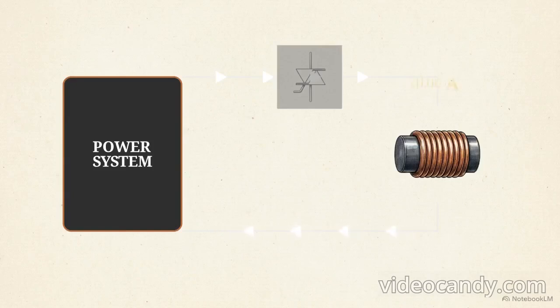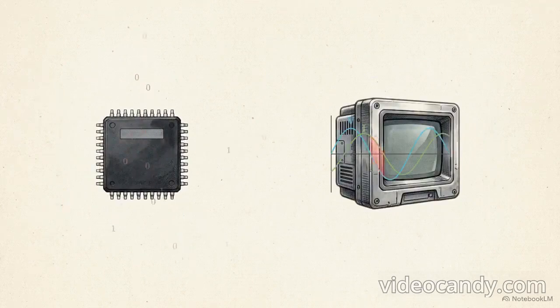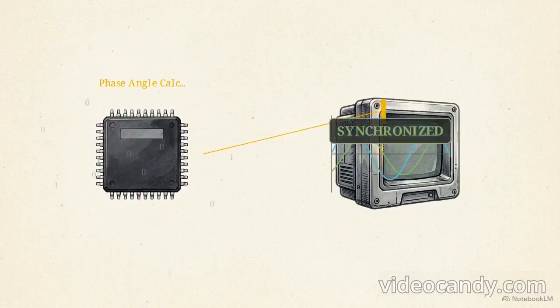This occurs because the inductor stores energy in its magnetic field. When the SCR attempts to turn off at the voltage zero crossing, the collapsing magnetic field forces the current to continue flowing. This stored inductive energy acts like a temporary generator, feeding back into the system and causing the load voltage polarity to reverse until that lagging current finally decays to absolute zero.